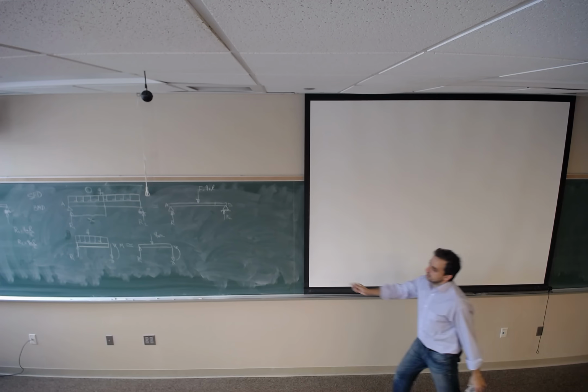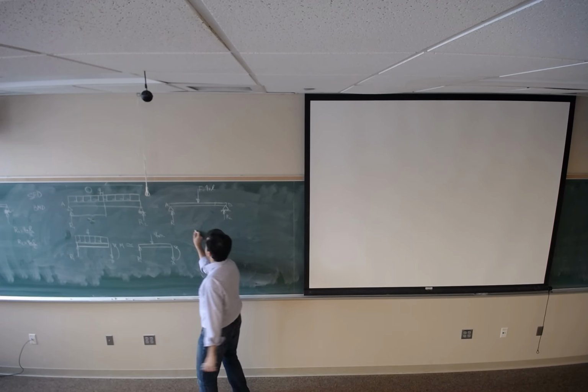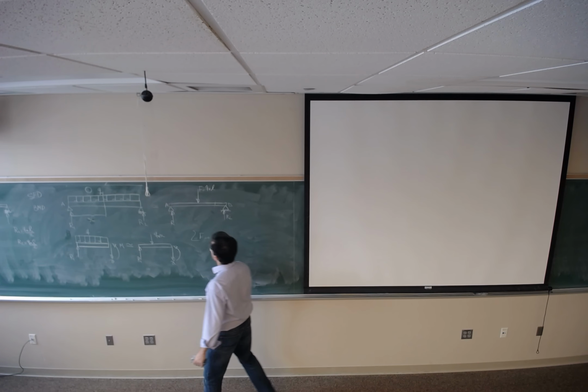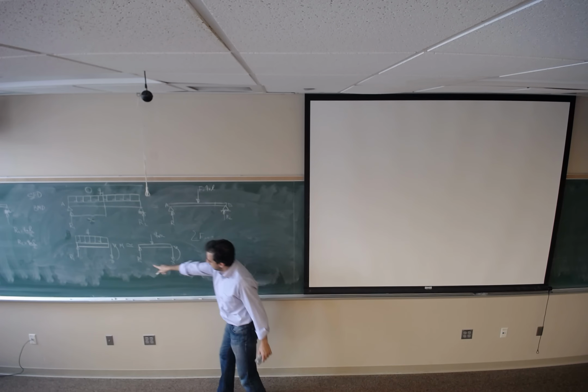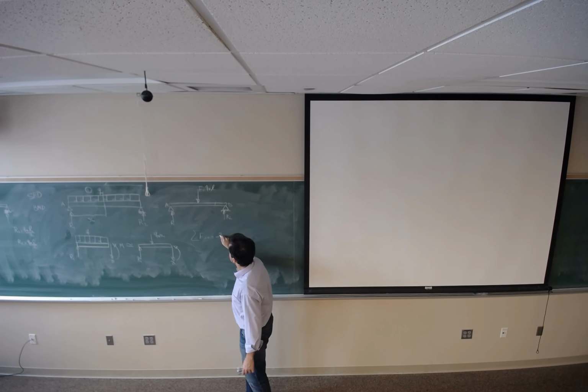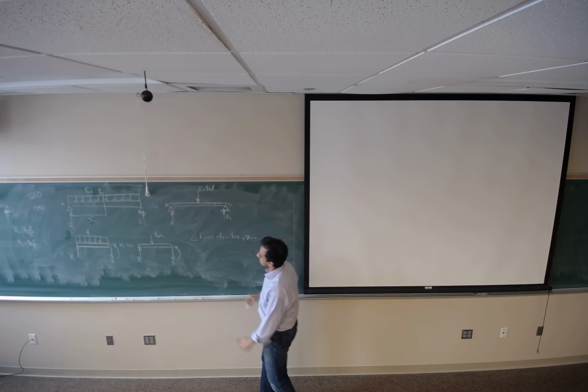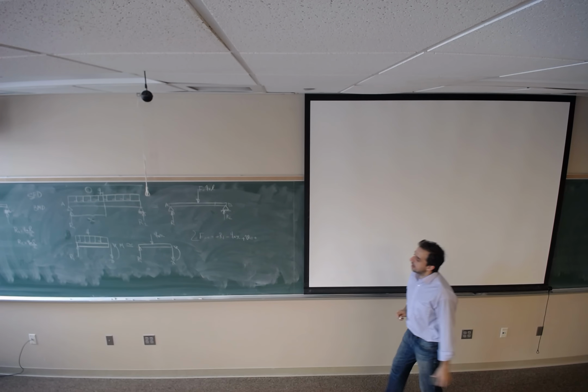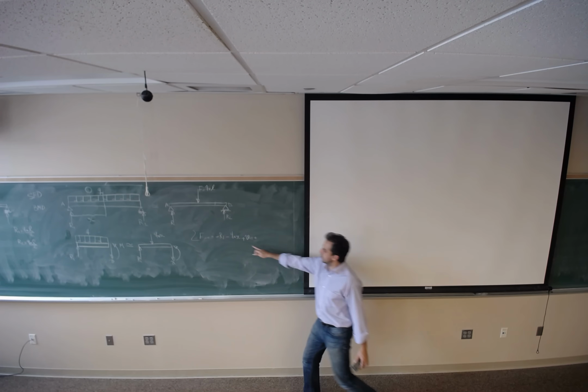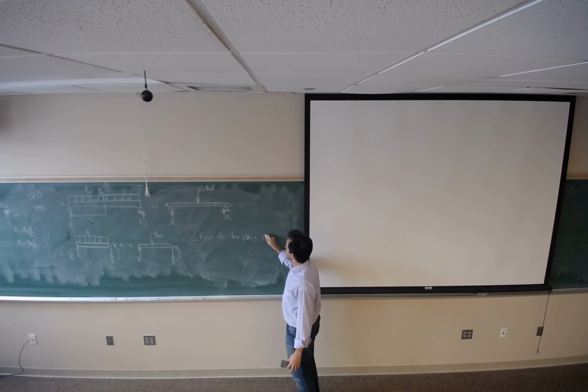Now I have the standard form of the section that I cut. I can write sigma F equals 0: negative R1 and negative Q times X, positive V equals 0. This is positive R1. So positive R1 minus Q times X plus V equals 0. V is going to be Q times X minus R1.